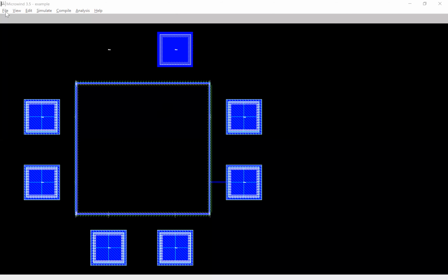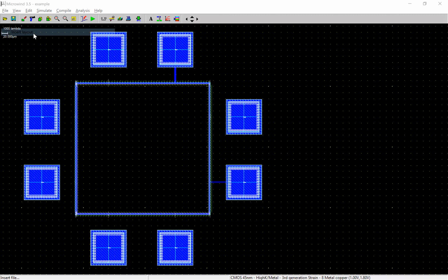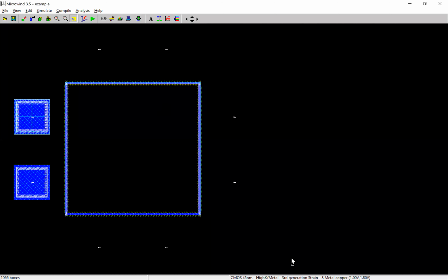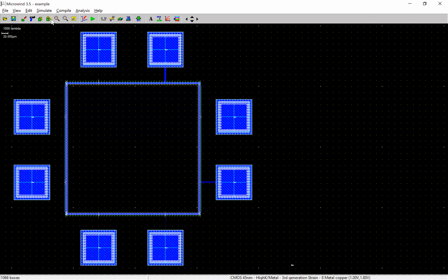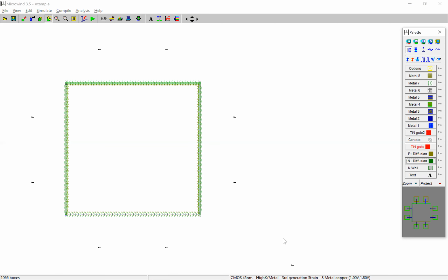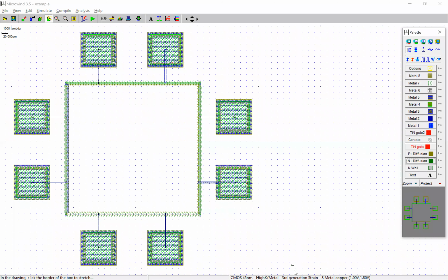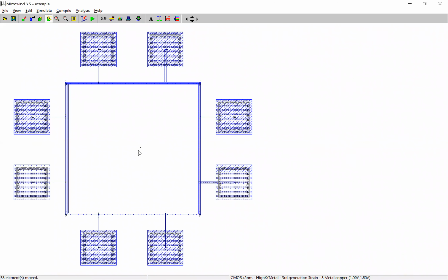And now we can just insert a NAND gate design. I just go to file, say insert layout, and select the NAND gate, any of the NAND gates which you guys have made earlier. It'll come on the bottom right hand side. Generally it comes on the bottom side, and we can take the move option. Maybe I just change the color of the background to white. The refresh rate becomes faster. I just select that move option and place it somewhere on the center of it, anywhere.